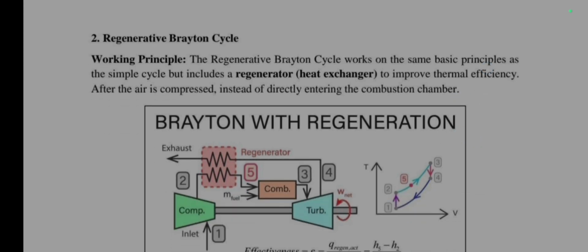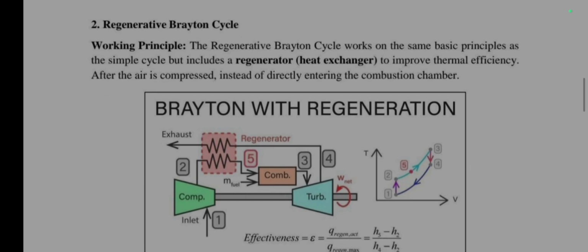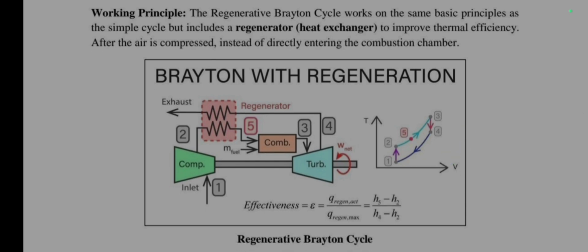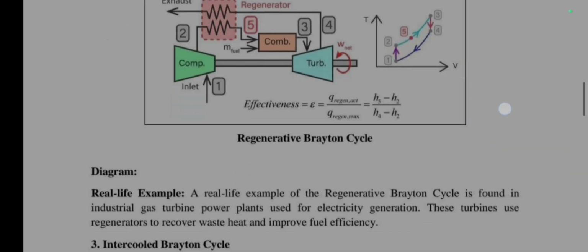Regenerative Brayton cycle. Working principle. The regenerative Brayton cycle works on the same basic principle as the simple cycle but includes a regenerator or heat exchanger to improve thermal efficiency. After the air is compressed, instead of directly entering the combustion chamber,